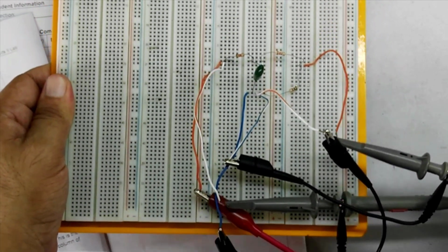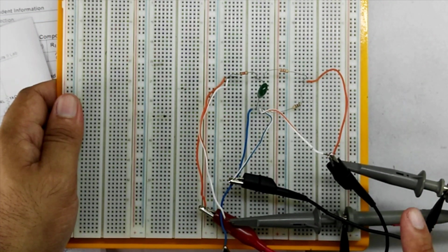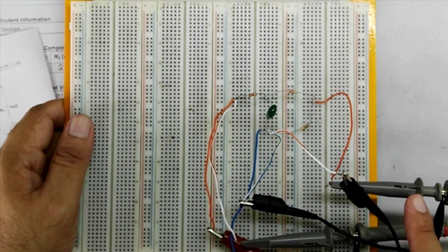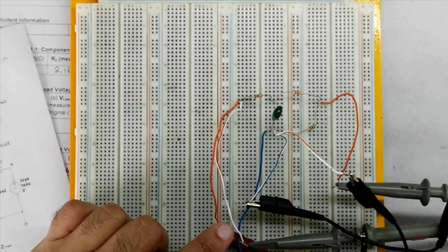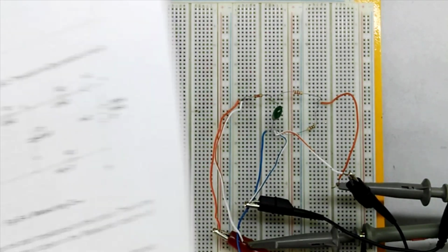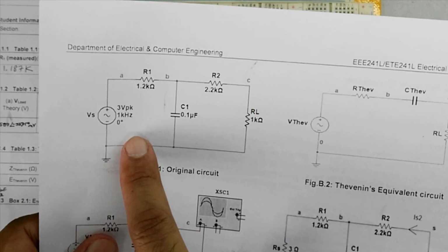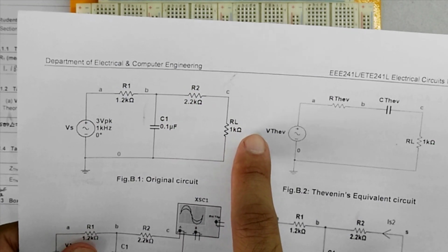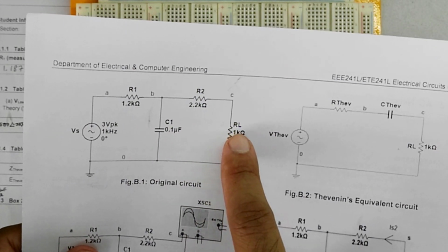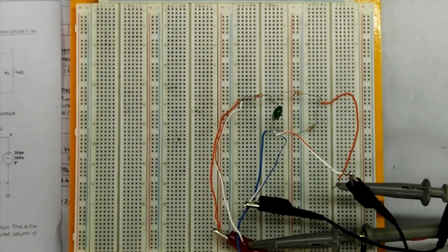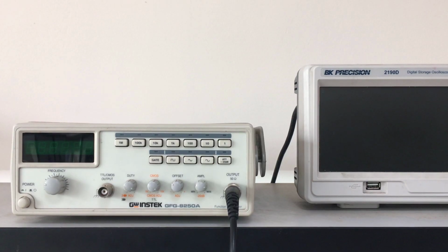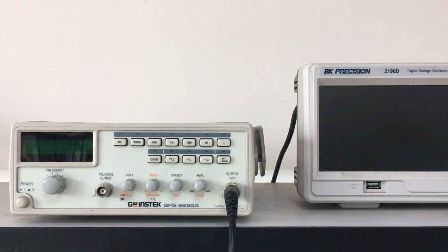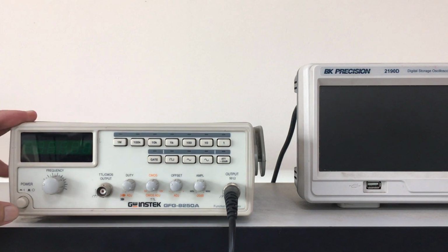So now our circuit is complete, and we have attached both channel 1 and channel 2 of the oscilloscope with our circuit. So from channel 1 we'll calibrate the source to our required 3 volt peak voltage, and from channel 2 we will get the voltage drop across the load resistance RL. So after completing the circuit, now we move on to the function generator and to the oscilloscope, where we will take the reading. So firstly, I turn on the function generator by pressing the power button,